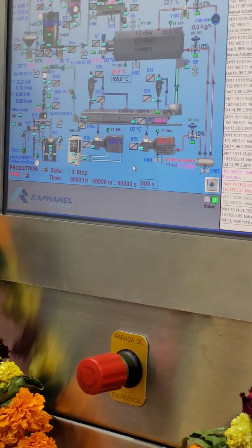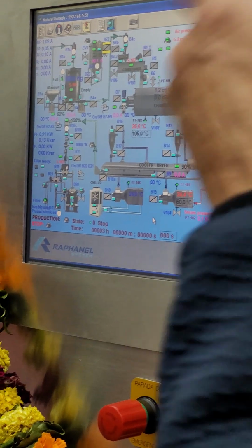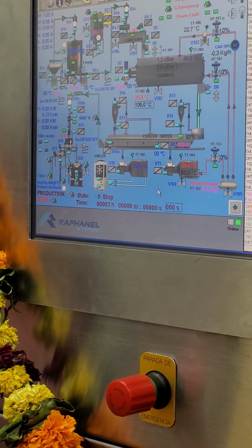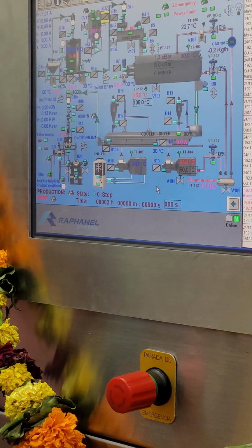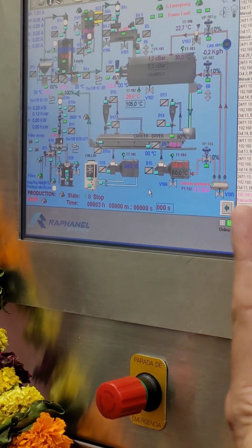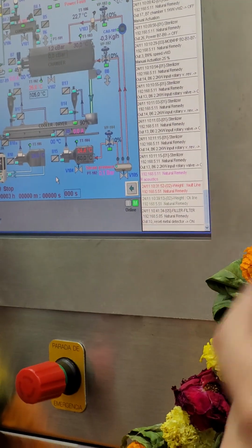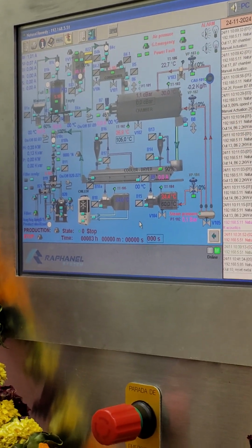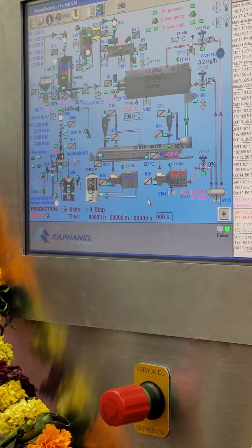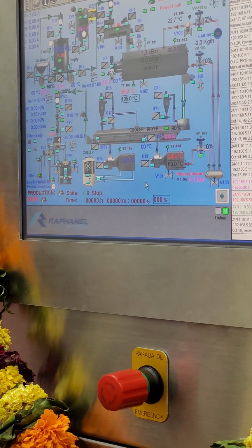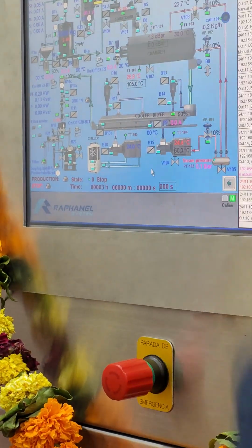Okay. You have to try to adjust the quantity inside the doser to the time you have left in the day. If you go home at 6, you have 1 hour to finalize. If you are working at 1 ton per hour, for instance, I don't know the bulk density of the material, but if you have material there for 1 hour, and you have 1 hour to go home, it's good. You don't need to load more.